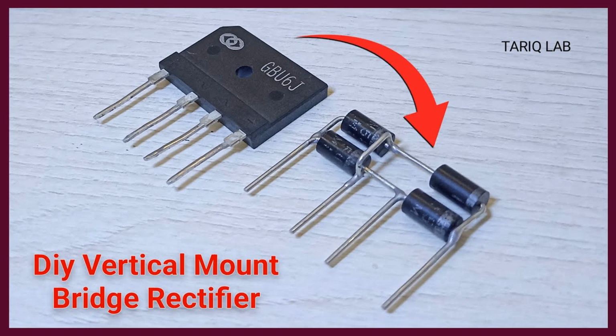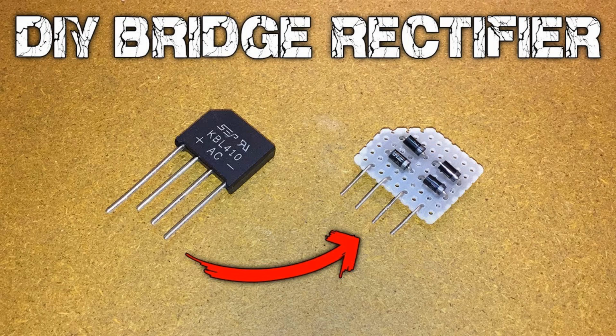Direction control. In addition to speed control, motor drives often require the ability to change the direction of rotation of the motor. Bridge rectifiers, combined with reversing switches or control algorithms, allow for seamless reversal of the polarity of the DC voltage supplied to the motor, thereby changing its direction. Current regulation. Motor drives may incorporate current regulation features to limit the amount of current supplied to the motor, protecting it from overload conditions. The bridge rectifier, along with current sensing and control circuitry, helps regulate the motor current to ensure safe operation.